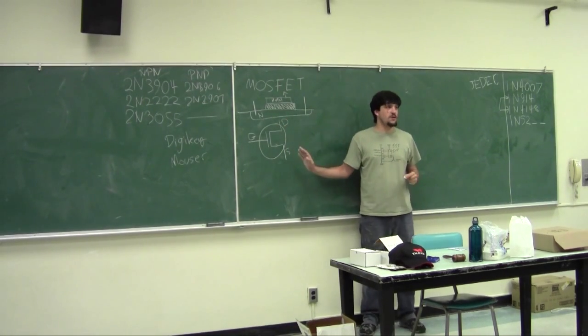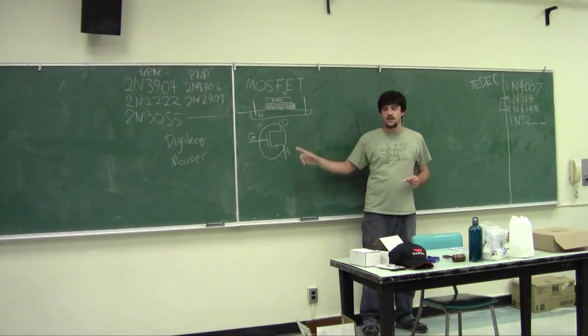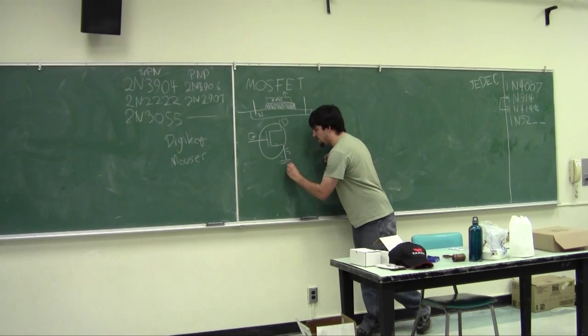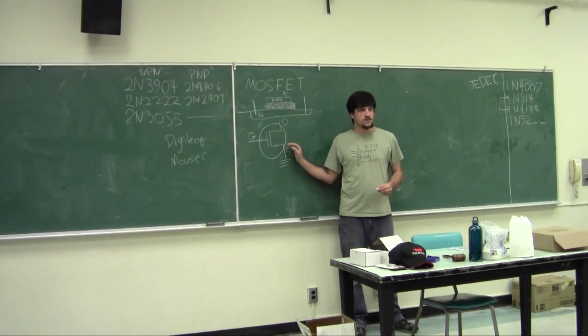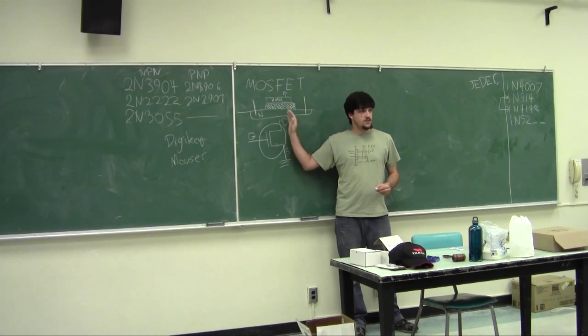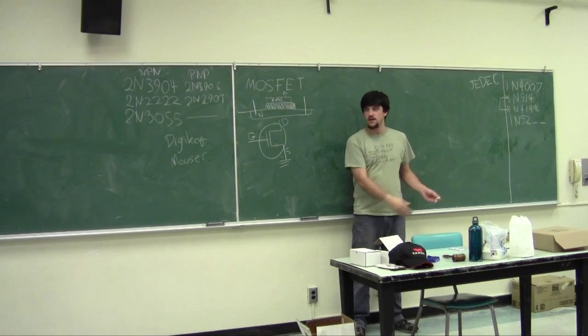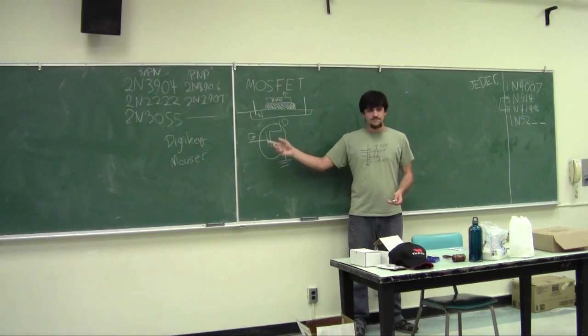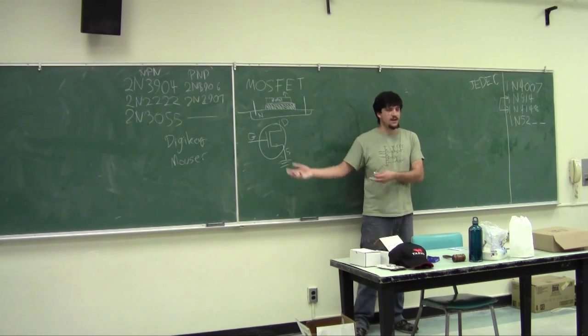Again, thanks to Benjamin Franklin, the mnemonics for source and drain are very confusing in that the source is negative on an N-channel MOSFET, and it then is the source of electrons that then flow through the MOSFET to the drain, right? Much like a faucet is the source that then runs to the drain. Benjamin Franklin, like, there was a 50-50 chance that he got it wrong.